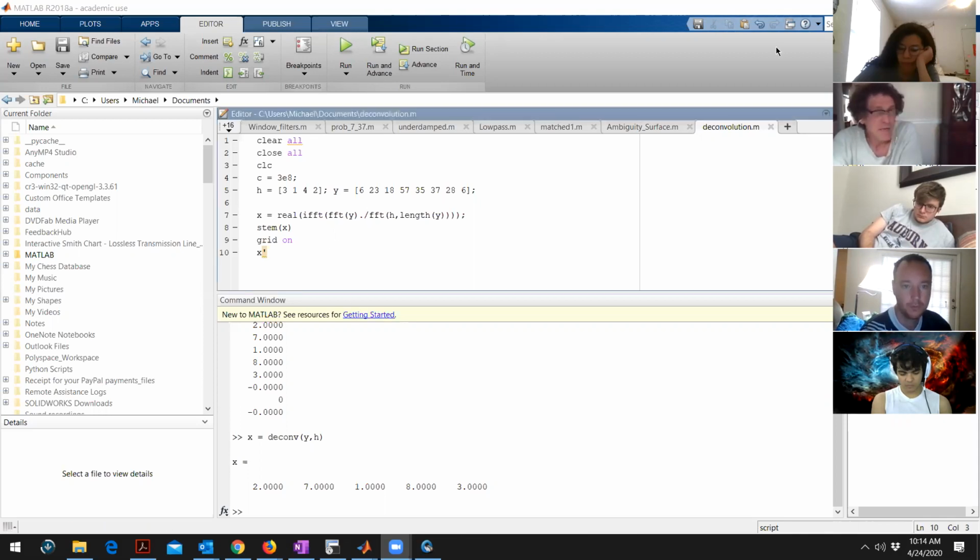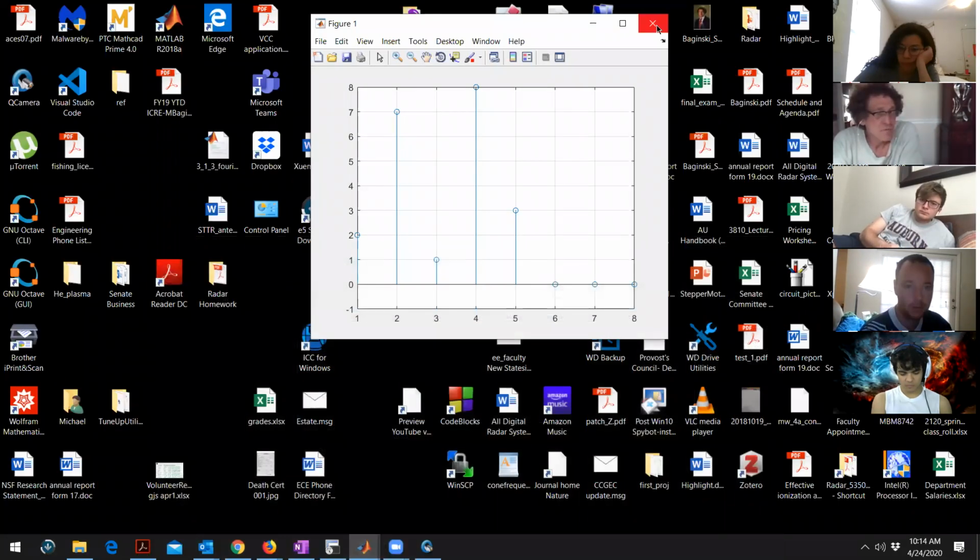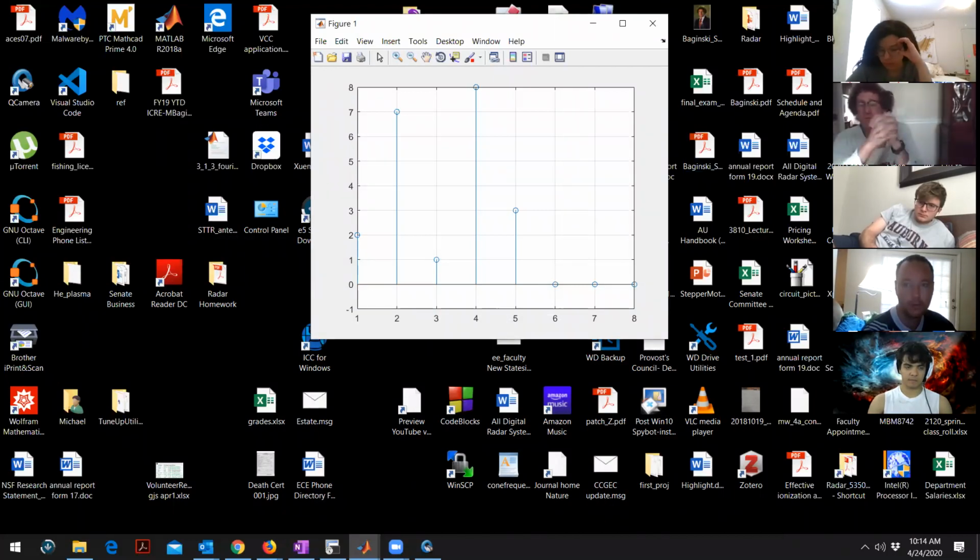All right, getting back to it, any other questions about the last homework at all? I had a question about how on some of the questions they would specifically say this is the minimal. Oh, it's minimum phase. That just means that the poles and zeros of the transfer function H of Z are all within the unit circle, and that means it's stable. That's all minimum phase means. So if it doesn't specifically say that it's minimum phase, do you have to discern whether it's stable or unstable, or can you just assume that it's stable?